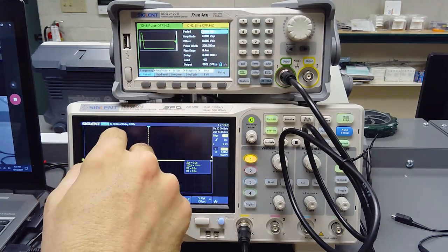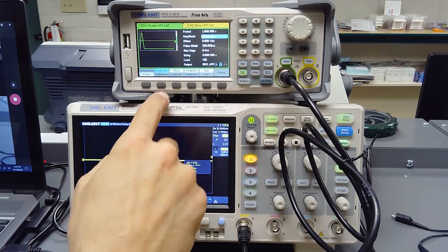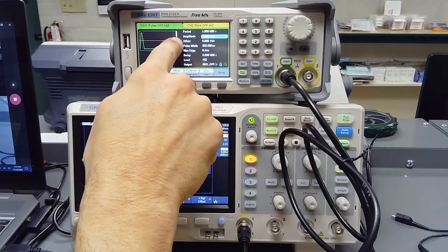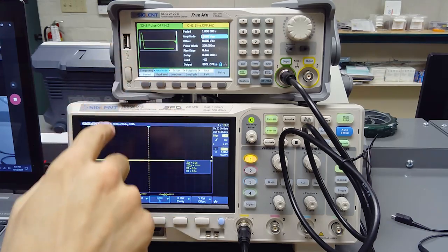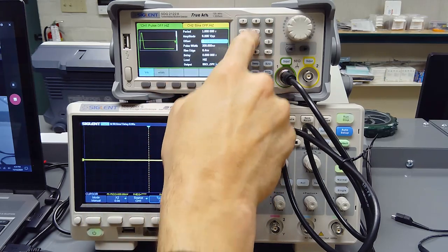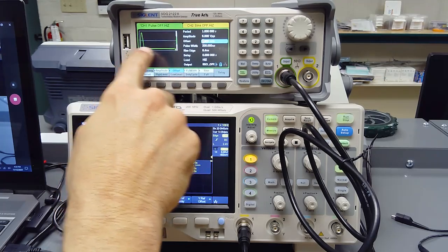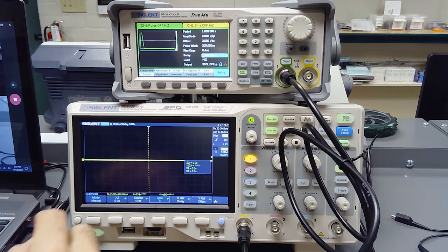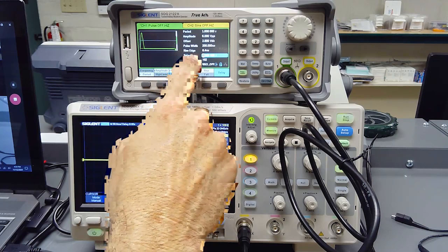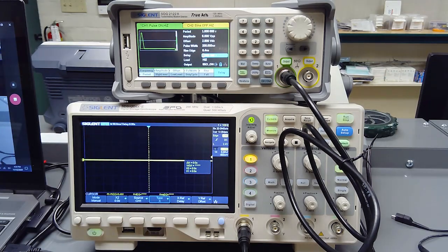Now I want it to be a 5-volt signal, so we'll go to amplitude. I'll say 5 volts peak to peak. And then I want it to start at 0 volts, and I want it to go to 5 volts. Not the way it is right now, where it starts at negative 2.5 volts and goes to positive 2.5 volts. So that means my offset has to be 2.5 volts. And when I press this, watch what happens to this green line. It moves down to the bottom of this pulse. Okay? And then, let's see, do we need anything else? So we're going to enable the output, and let's see what this looks like.